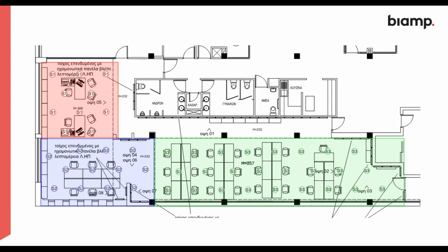Very key, an interesting one here. Can we install the emitters closer than 60 centimeters to the wall if the corridor is less than 1.2 meters? Yes, the answer to that is we will have to. So the rules that we've gone through are in the ideal world. In applications like that, where because of the architecture there is nothing we can do, then we have to accommodate those accordingly.